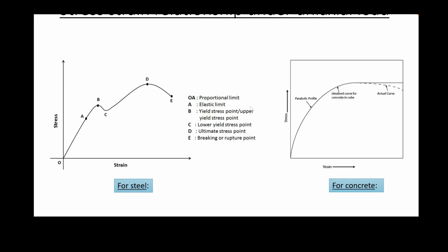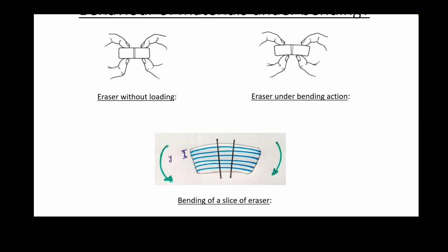We'll start the problem. If the question asked is what is the total compressive force at the time of failure of a concrete cube or cylinder, we can directly take the appropriate stress value from these familiar stress-strain curves under uniaxial compression, and we would have answered the question. These graphs we are well familiar with. Now the question is how we can use this for a beam. To answer this, we need to first understand how a beam deforms. Okay, let us see that.